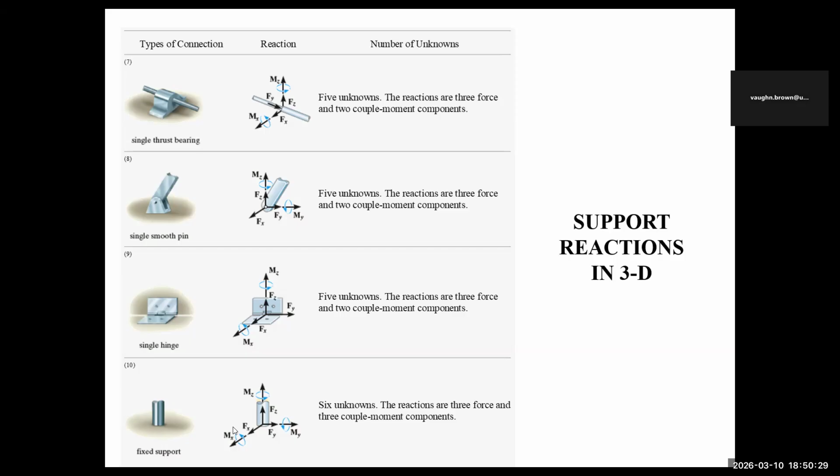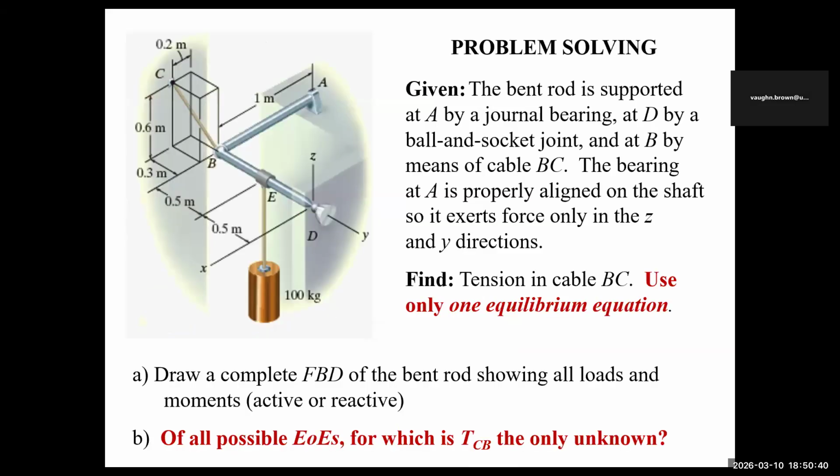So it's a fixed support. I wouldn't say pin, it's a fixed support. So it's like a cantilever, but it's a fixed support. Reaction in all three, moment in all three. Six unknowns. So note those, please.